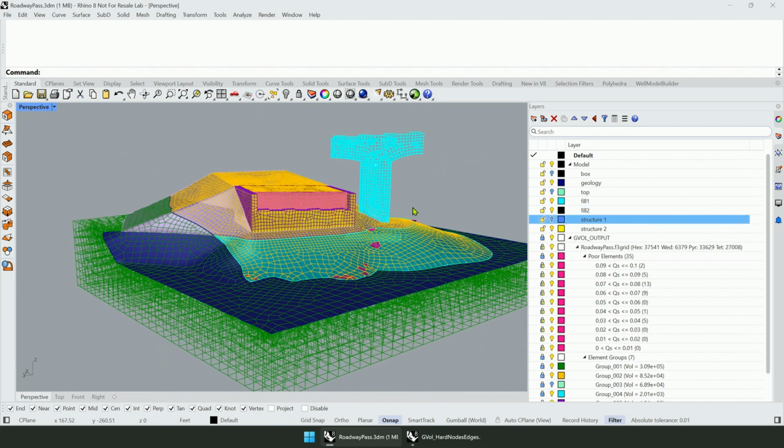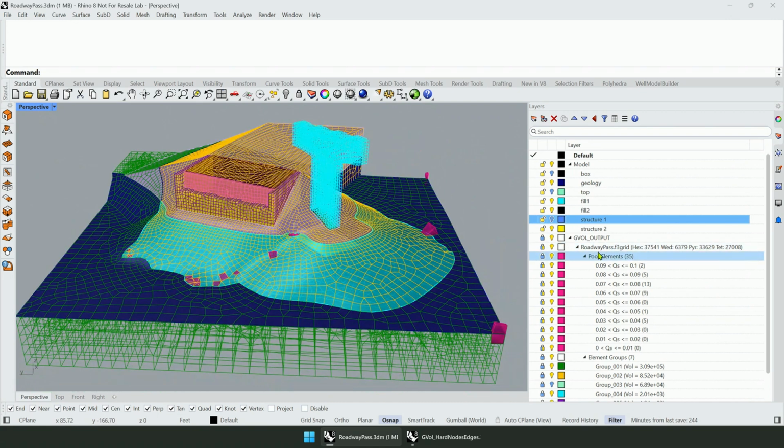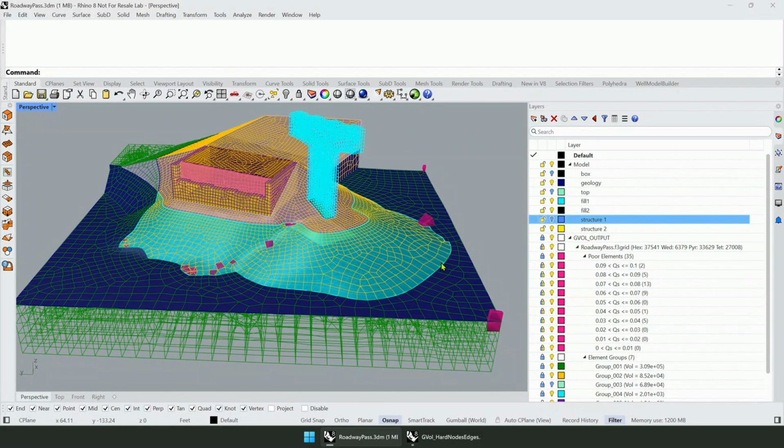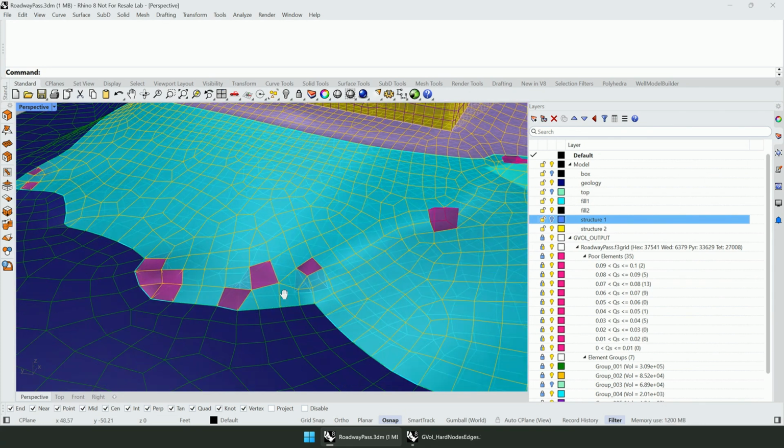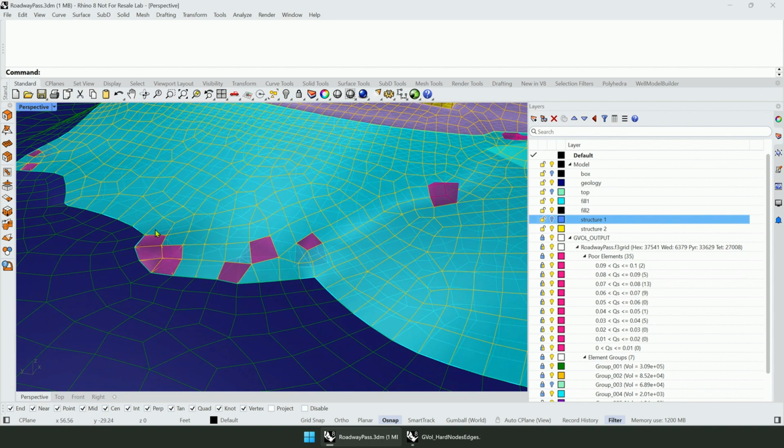But an important thing I wanted to note here is information about poor quality elements. It's very important to pay attention to poor quality elements with lowest quality. We don't get those here because it's overall a pretty decent mesh, even though we got some average quality elements. But when we look at where they are clustered, we can see that there are quite a few elements here.